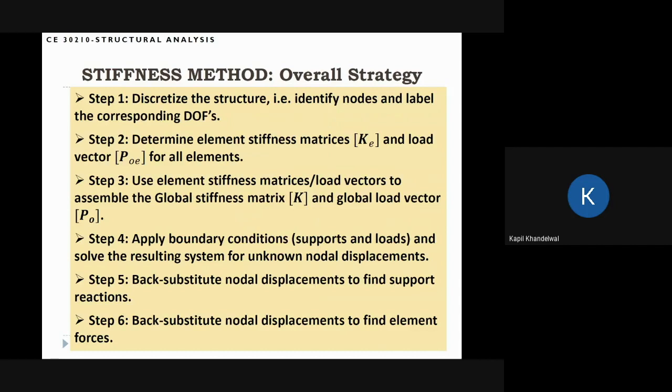As we have discussed earlier, you don't have to worry about labeling the degrees of freedom, but it's always important if you can choose a correct strategy. For example, especially for trusses and when we are doing problems by hand, it's always important to label the free degrees of freedom first and the supported degrees of freedom later. This helps with the organization of the entries in the final stiffness matrix.